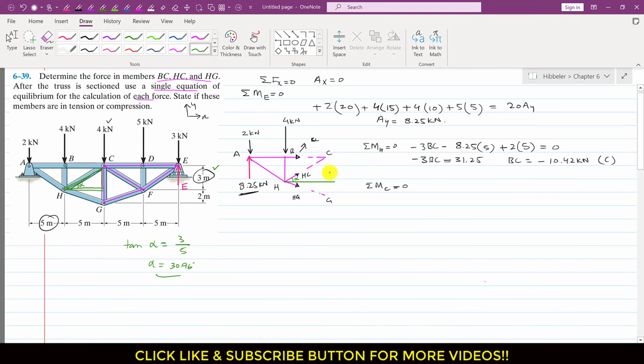So this Hc is making 30.96 degrees with the horizontal, and similarly this Hg is making some angle. Let's say this angle is theta. To find this theta, we can use this lower triangle, right? If I apply tan theta, tan theta will be equal to this perpendicular, which is 2 meters, and the base is again 5. If I take tan inverse of 2 by 5, this gives me 21.80 degrees. So this Hg is making 21.80 degrees with the horizontal, right?